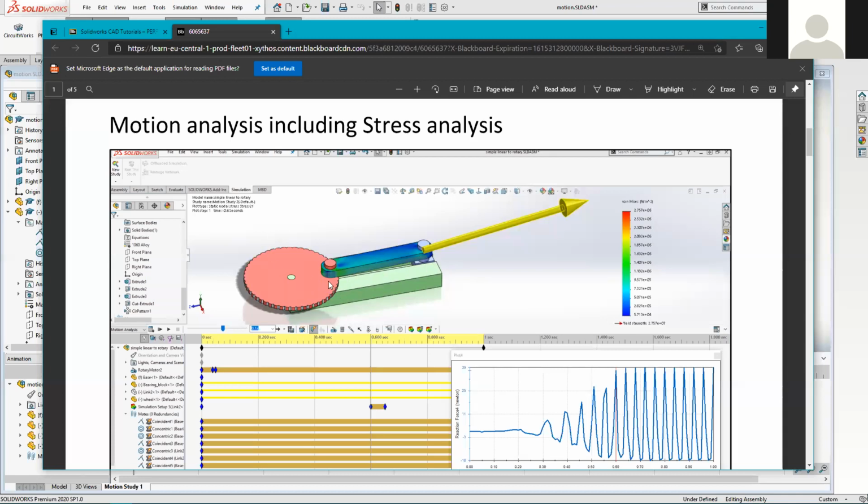And as all that is happening, the link will undergo compressive and tension forces as the bearing block initially doesn't want to move, because we're disregarding friction. I mean, it's in this simulation, but it's not the main force. It's just the fact that the bearing block has mass means it's resistant to moving initially. And then once it gets accelerated up and it starts traveling along here, it then has to be decelerated, and then it has to accelerate in the opposite direction. So the link sees compression and tension and compression and tension.